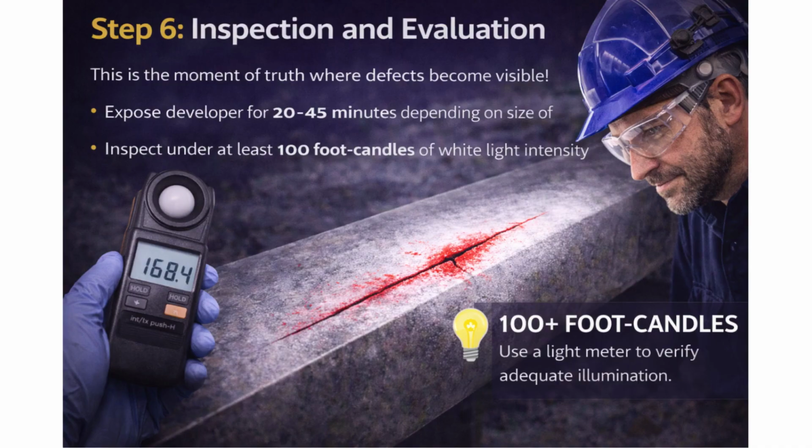Step 6. Inspection and evaluation. This is the moment of truth where defects become visible. The time of developer exposure can vary greatly, as larger damage is usually visible sooner and smaller cracks become visible much later, typically taking between 20 and 45 minutes.